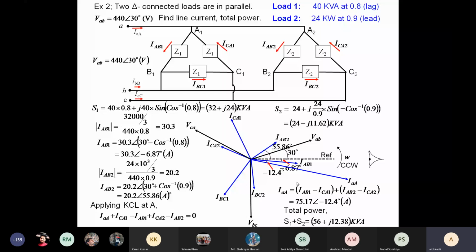You have to do it very carefully, handle it by a similar approach, but be very alert about the phasors and what is going on, and all the angles have to be done correctly. There can be problems with a mixture of loads, multiple loads, some star connected, some delta connected, and you are asked to find the line current.